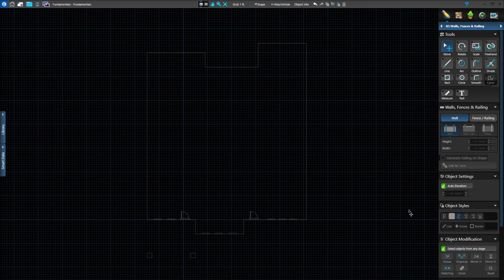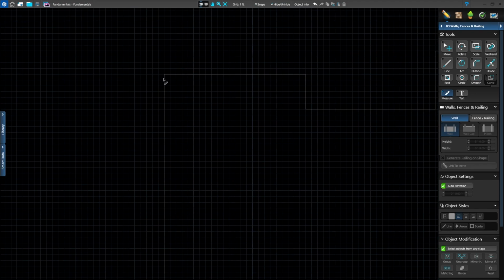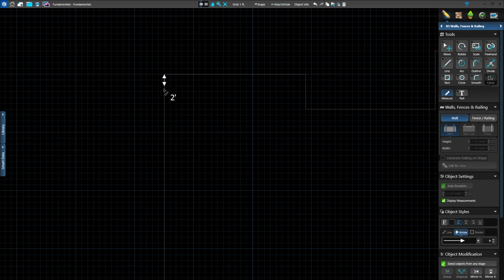We're going to measure where the wall is going to go using our measure tool. That's something we haven't done yet. In our tools, we have our move tool, line tool, rectangle tool, and just below that we have the measure tool. Left click on the measure tool and then go to the top left-hand corner of the house. Go ahead and zoom in fairly close so you can really get to that corner easily. I'm a big fan of the zoom tool. Left click there, and then we're going to measure down 16 feet. So you can just stretch that down when you get to 16. Left click. Could have typed in that value as well. So that's always an option when you're drawing or measuring.